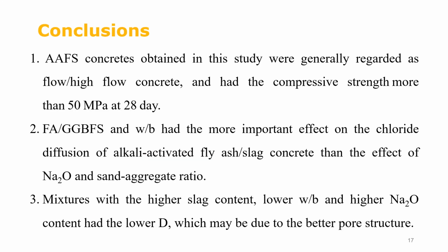To sum up, firstly, alkali-activated fly ash slag concretes prepared in this study were generally regarded as flow or high-flow concrete, and they had a compressive strength of more than 50 megapascals at 28 days.